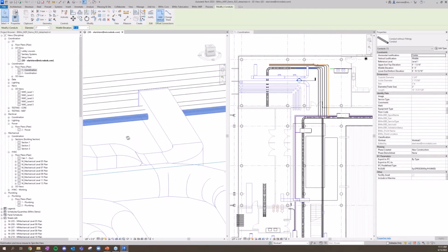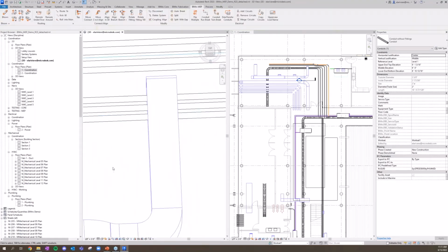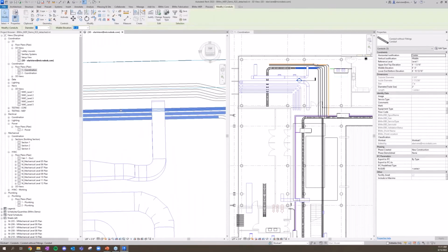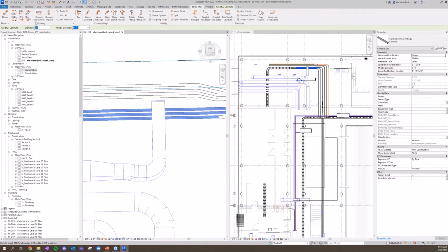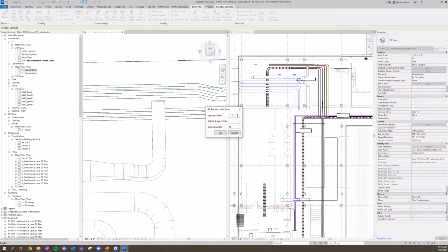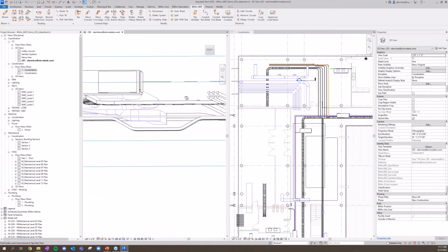If we take a look, I've got a little clash sitting right over here with that ductwork, right? Now it's generally up to me to fix that clash. So I've got a very quick way to do that. I can actually pre-select all of these elements, use MEP, and I can use this over or under, cutting someplace to the left, someplace to the right. Choose some vertical offset, maybe -10 inches. And a bend that makes sense. For electrical, 30 makes perfect sense. I can say okay, and it's gonna automatically cut and create that for me. And there we see, peeling down.